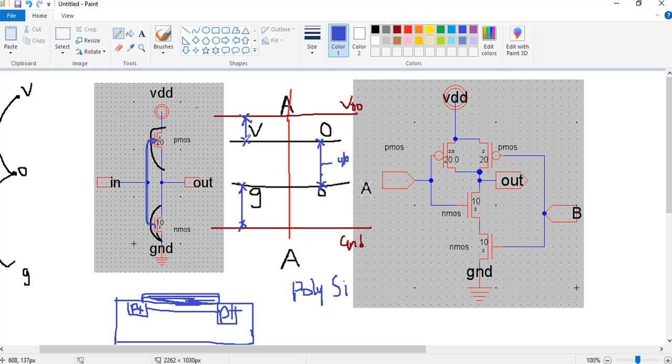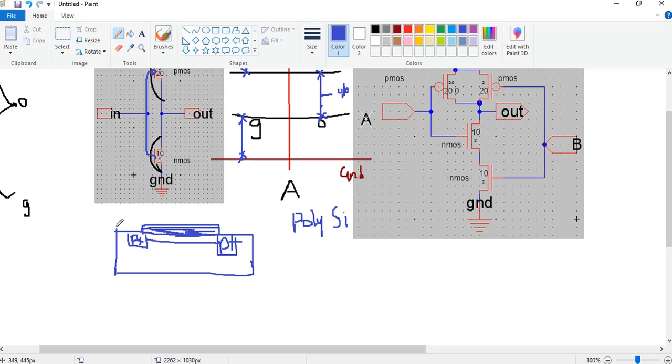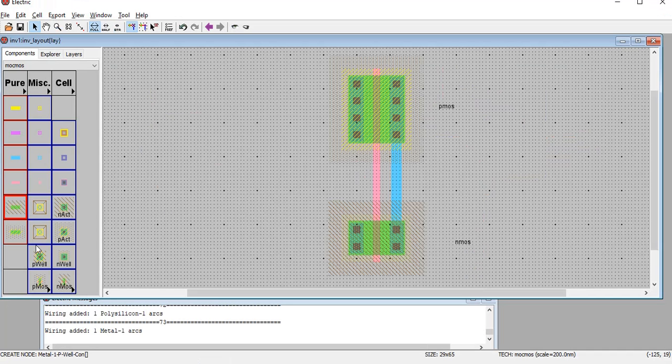And when we connect the VDD, one more thing was connected over here, and that comes down over here. As you can see, when we have the MOSFET, if I have a PMOS, it will always be based on the N substrate or N well. So all these are connected to the N substrate. In order to have the connections in a proper manner, I should also have the N well, since I am dealing with the PMOS.